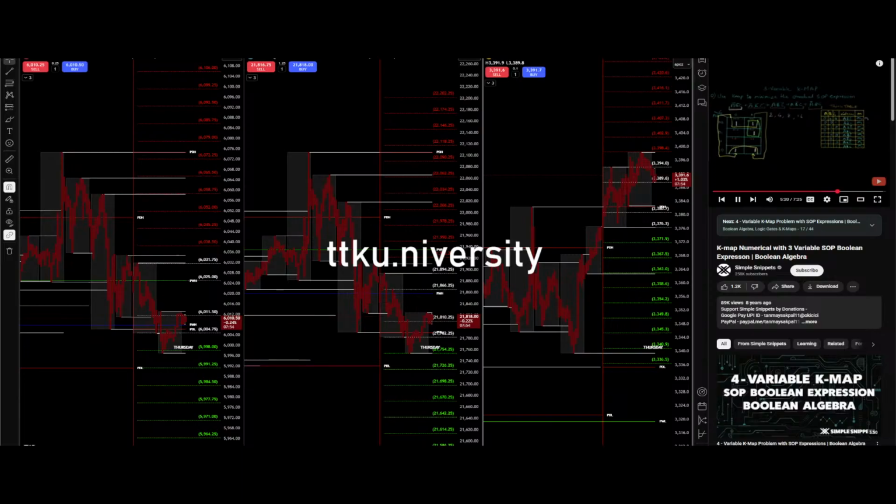So after grouping, how do we go ahead and simplify? Let's see for the first group what all binary values we have. For the first group we have 0 0 0, 0 0 1, 1 0 0 and 1 0 1. Now the way we simplify these is we look for the common term. That is, in all these 4 different rows, which variable value does not change.